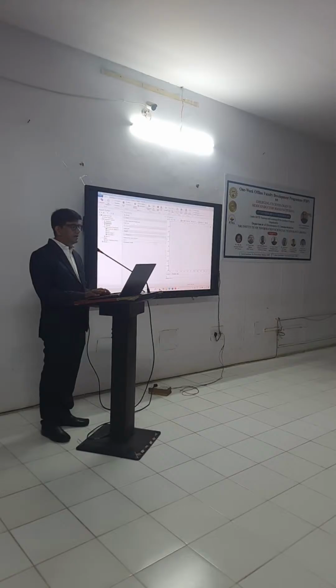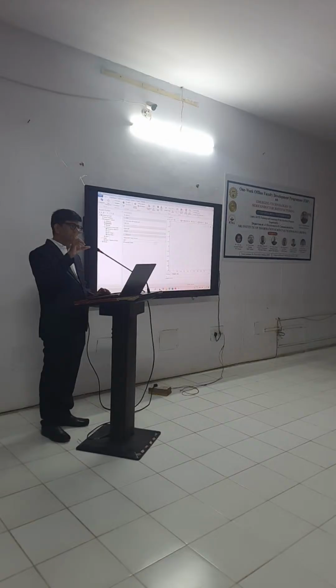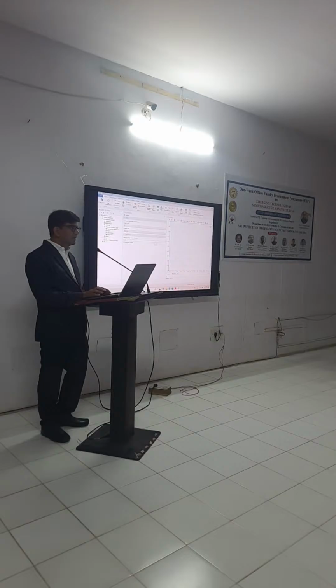So what I did till now: I have selected what kind of geometry you want, so I select 2D geometry. Then what kind of mechanics you want, so in that I select physics as piezoelectric devices. And then what kind of analysis is required, so we selected a frequency domain analysis. Then the next part comes, the geometry part.